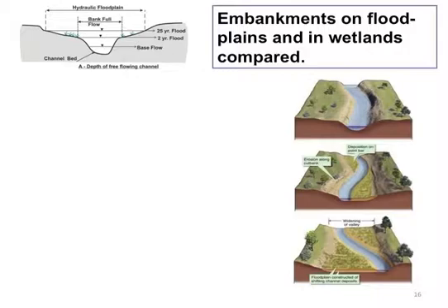Your 2-year, well, it's a range between 1.5 to 3-year return period flood will demarcate your bank full flow. Typically, that edge is also shown as the permanent vegetation line, so you can identify it in those ways. So the rest of this gentle slope here, you can have a 10-year or 25-year return period flood, and that will identify your hydraulic floodplain, depending on the frequency.